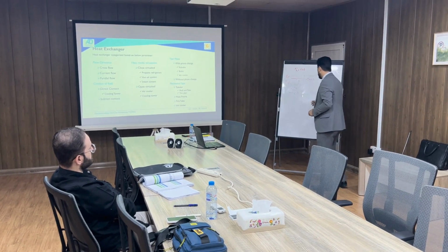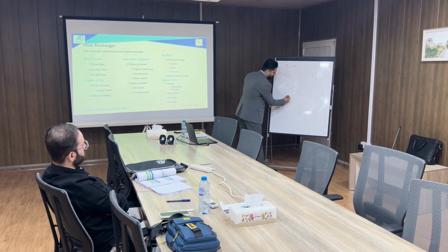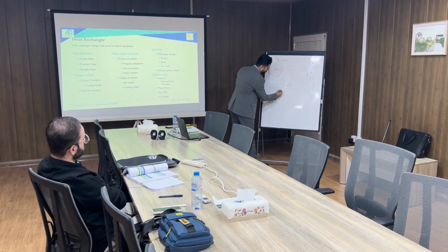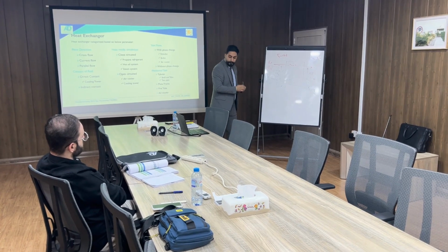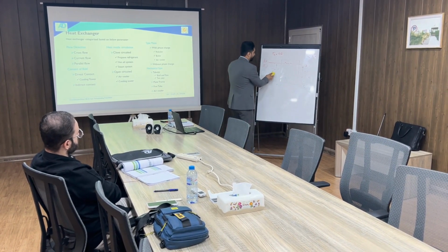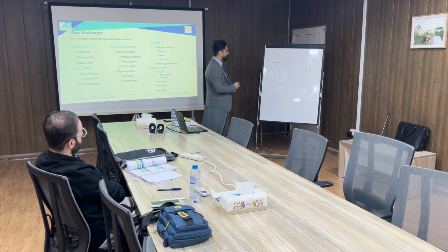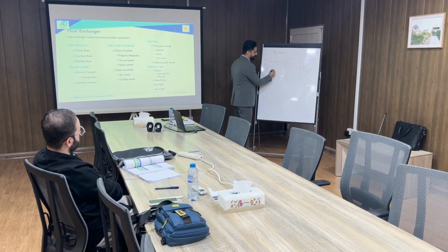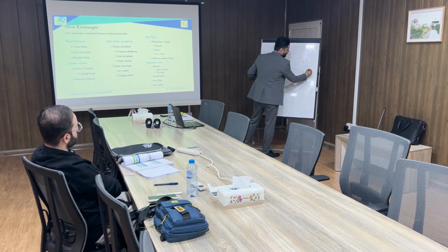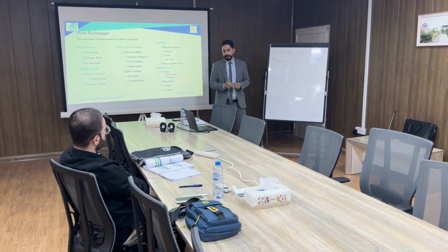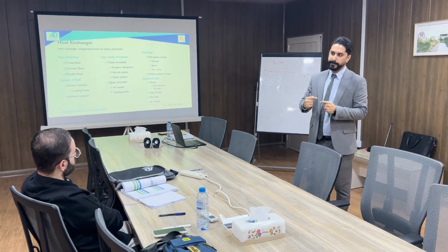So, if we consider the countercurrent flow, here it would be, for example, 19, and here it would be 16. It will provide a more uniform differential in temperature for heat transfer. Here it would be about 40 degrees Celsius, and here it would be about 30. That's why in most cases we prefer to use countercurrent flow in heat exchangers.